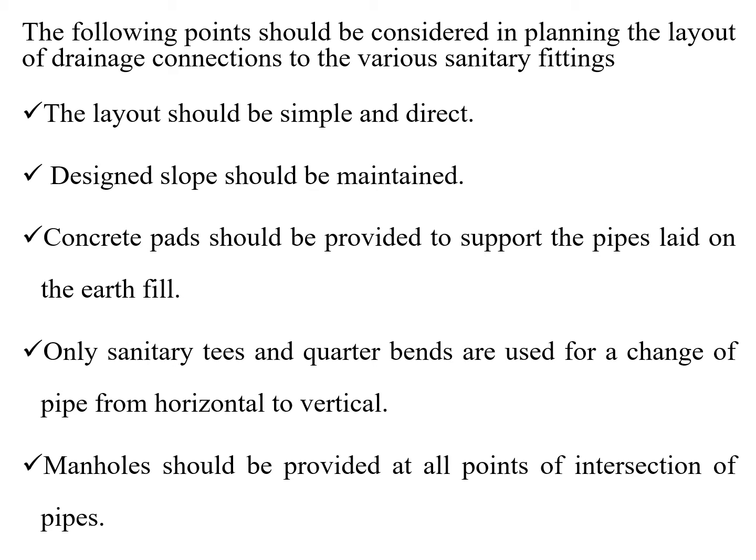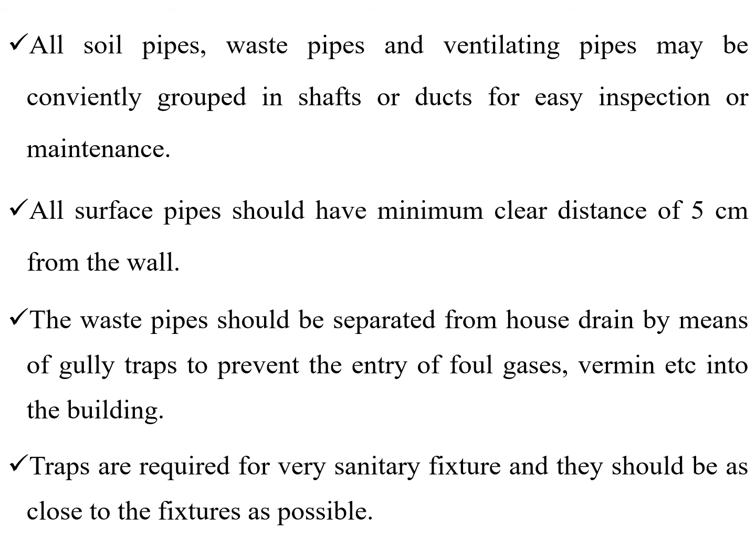Concrete pads should be provided to support the pipe laid on the earth fill. Only sanitary tees and quarter bends are used for change of pipes from horizontal to vertical. Manholes should be provided at all points of intersection of pipes. All soil pipes, waste pipes and ventilation pipes may be conveniently grouped in shafts or ducts for easy inspection or